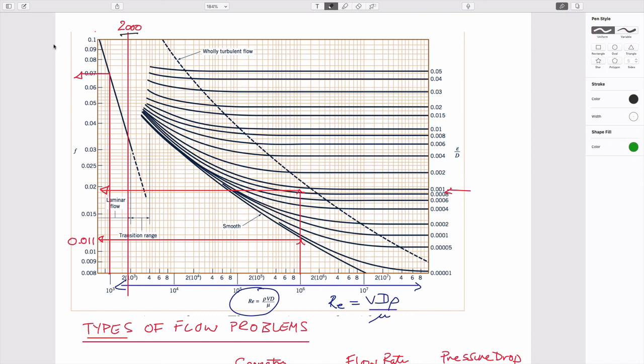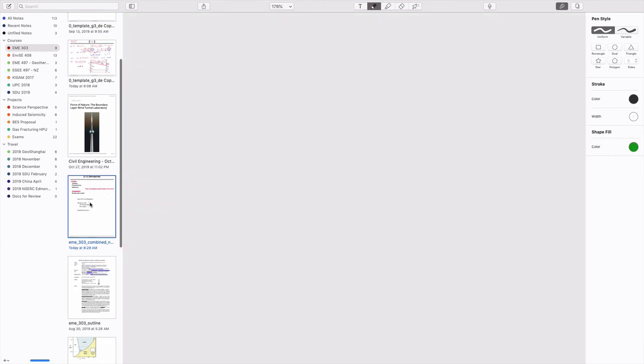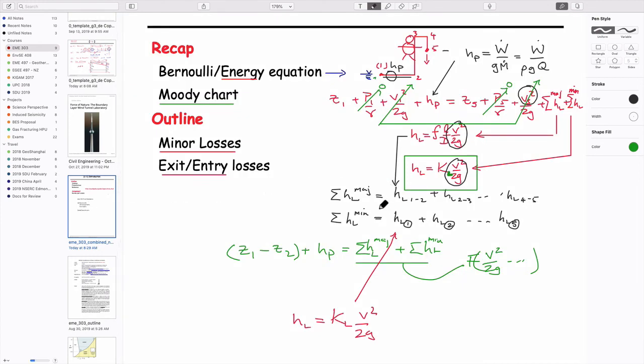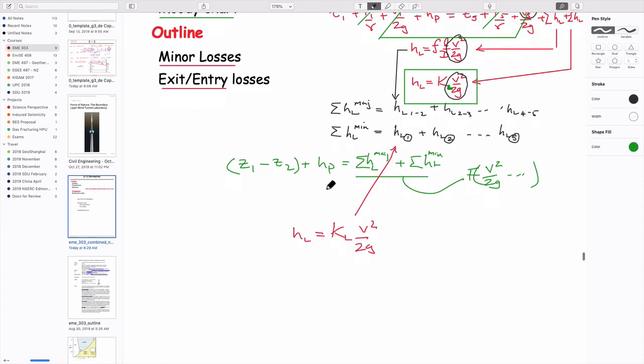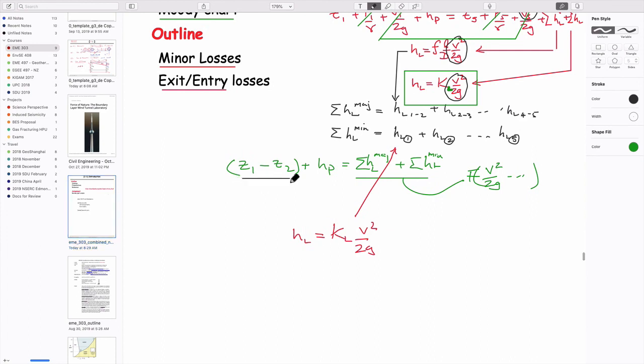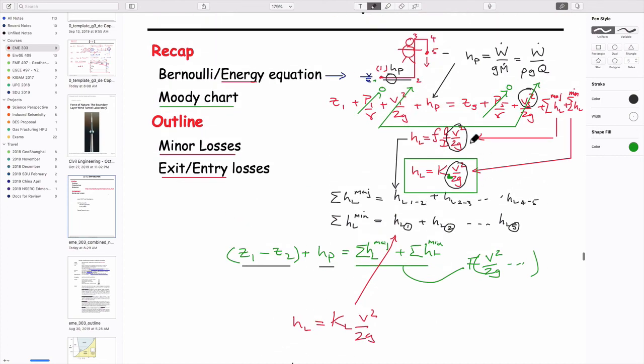frictional loss is. If you have a system which is not a simple one like this, but comprises a whole bunch of different components, like this umbilical through the guy and then squirting down on the water, then, because of continuity, if the cross-sectional areas at every point in that pipe are roughly the same, you could write this expression: the elevation difference here and the pump, which is what you want to solve for, is merely the sum of the losses, k loss 1 plus k loss 2 plus k loss 3, I guess till 5.